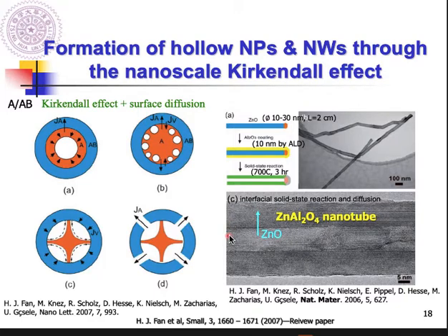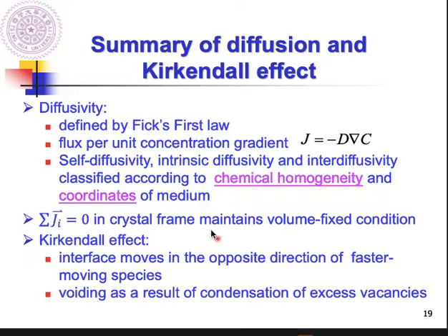Probably in the beginning it is a void, and based on the surface diffusion to lower the surface energy of the system, these tiny voids will merge together to form this hollow structure. So this is also an application of the Kirkendall effect in material synthesis. So I will give you a summary of diffusion and the Kirkendall effect.